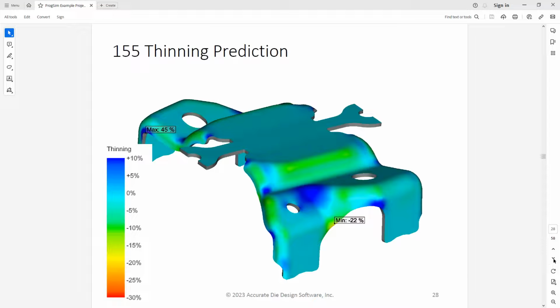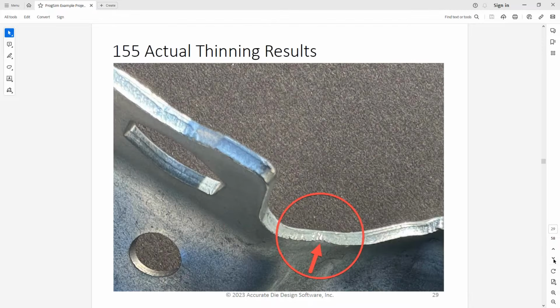And again, the blank development on this, we did this in 2005. And oh my gosh, I was scared. I have no idea what that blank looks like. Are you kidding me? Some people are a lot better at it, even without using any kind of flattening software. But you're just building a smaller die because you're not planning for so much material waste. There's that thinning. You can actually see it visually even. That's that 22% thinned area. Next.